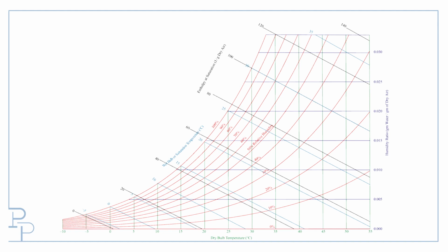I chose the psychrometric chart because this is the most common application of wet bulb temperature, so it's a useful tool for showing this difference graphically. In reality, you aren't going to find charts like this for all the combinations of chemicals you get. You can, however, perform thermodynamic calculations to get the wet bulb temperature and the dew point temperature of any combination of gases. Hopefully, this graphical method helps you differentiate a little bit better conceptually.